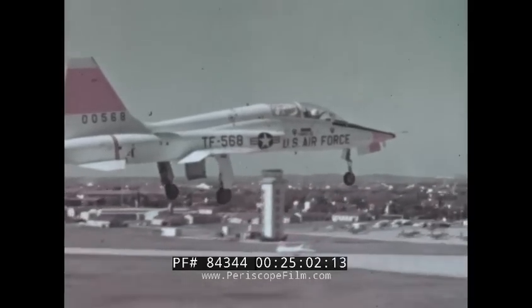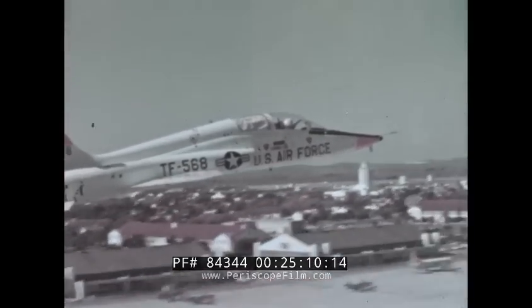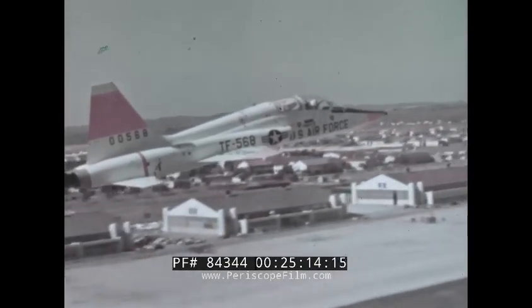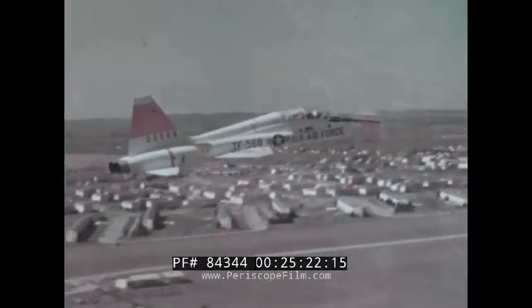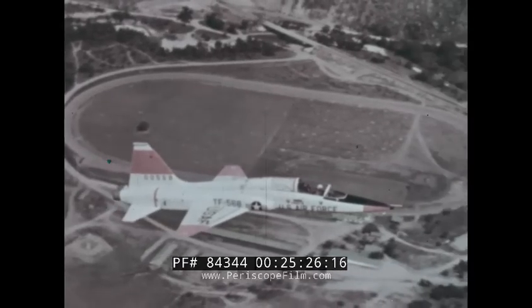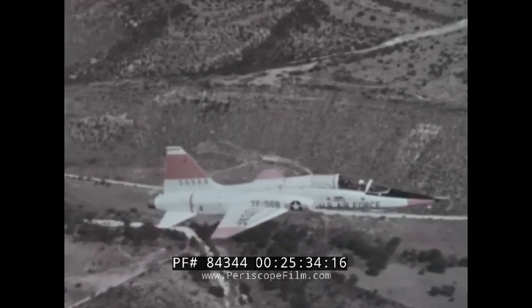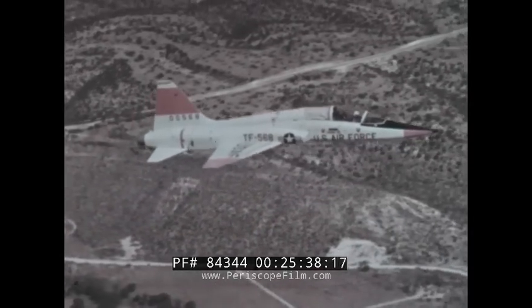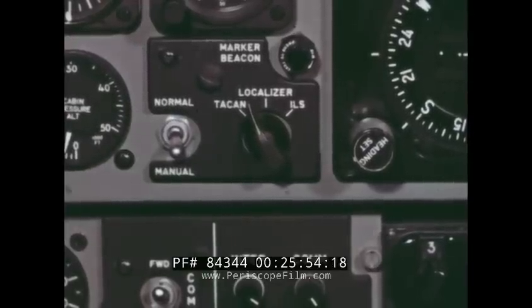Add 100% power and follow the same procedures as you did for your instrument takeoff. Accelerate to 220 knots and reduce power to 90%. Climb to the missed approach altitude at 220 knots. Turn the navigation mode selector switch to TACAN position and the steering mode switch to manual. We'll practice using the manual mode until reaching the base leg.